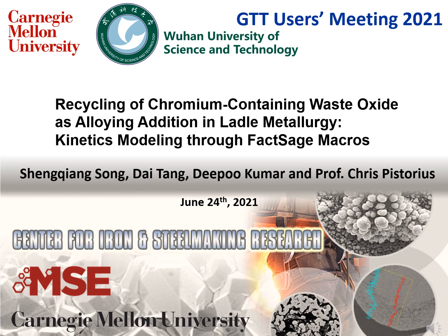Today, I'm going to talk about recycling of chromium-containing waste oxide as alloying addition in ladle metallurgy, especially using FactSage macros for kinetics modeling in the project. This project was done when I was at Carnegie Mellon University in Professor Chris Pistorius' group.